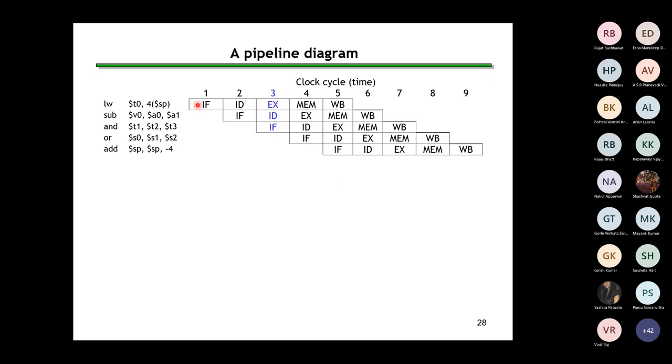And therefore, since my instruction is partitioned into different components and my hardware is also partitioned into different modules, I have overlap in time, but these modules are all different. They are active at the same instant of time. So this is where I'm getting maximum parallelism. Here you can say that the pipeline is full now, because every module in my hardware system is now busy.